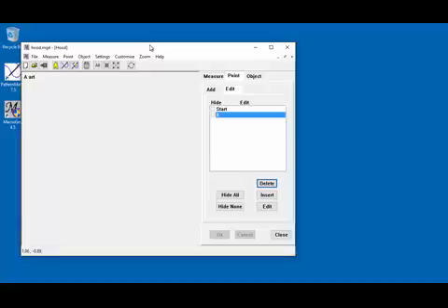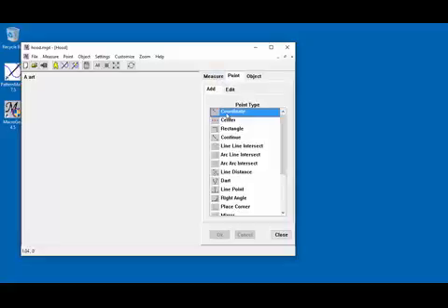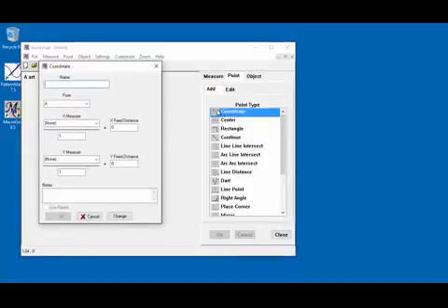Add point B. Let's add a second point. We're going to draft a rectangle whose width is 1/2 the neck measurement, so let's mark this out. We're going to add a coordinate point. This will be measured from point A. It got that automatically. We're going to call our new point B. It's measured from point A, and we're going to use the neck measurement. We're going to scale it by 1/2. Okay, looks good.